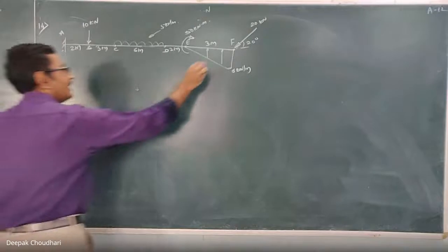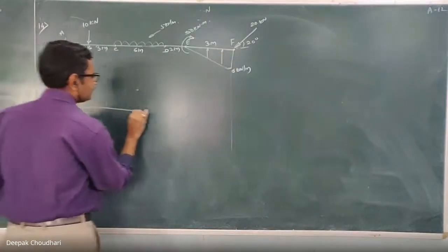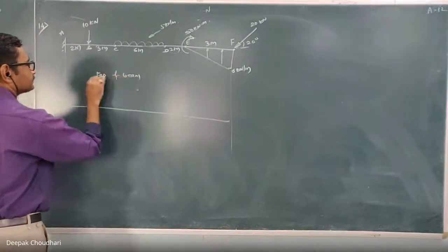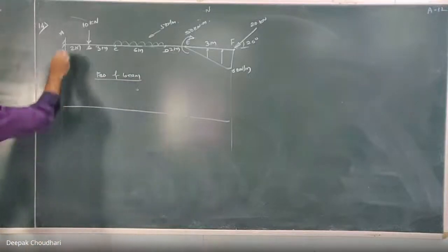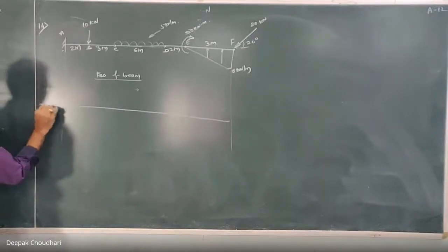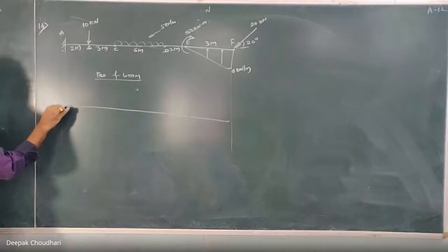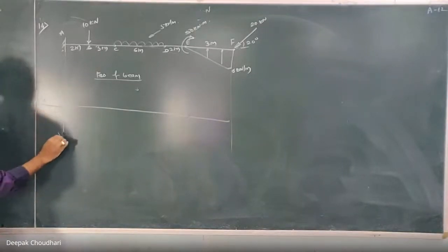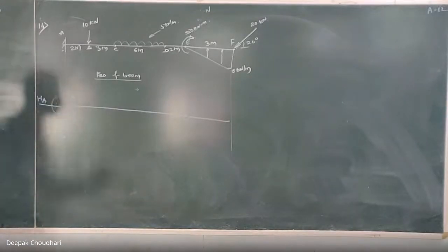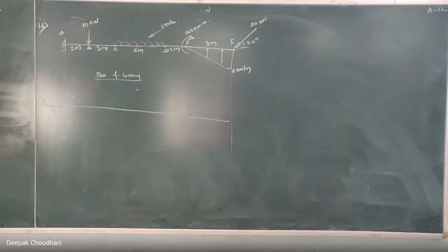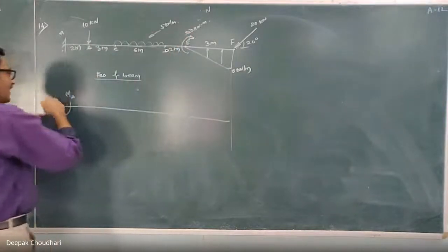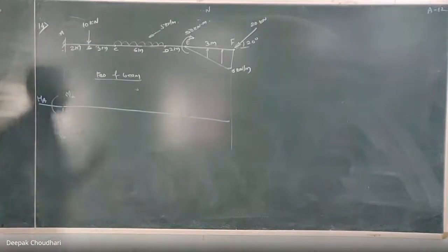Yeah, so first let's draw the FBD of this beam. At point A, there is a fixed support. कितने unknowns आएंगे यहाँ पे? There will be 3 unknowns. Here, one is a horizontal component of reactive force, other one is a vertical component of reactive force, and third one is a reactive moment. Let's denote this as a reactive moment at point A, MA. It is a reactive moment exerted by the support on the beam. This reactive moment is similar to this moment. खाली ये moment इधर act हो रहा है, ये moment इधर act हो रहा है. Okay. Here it is a reactive moment.